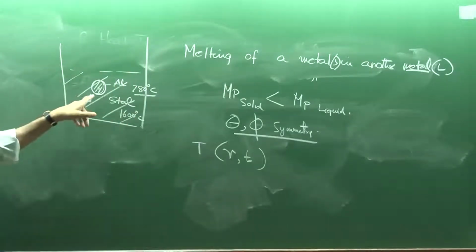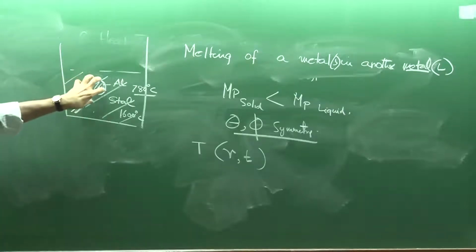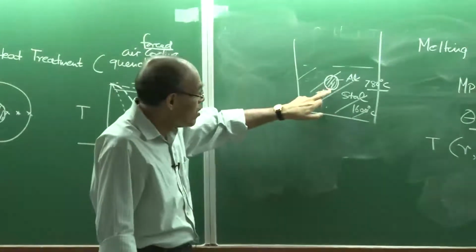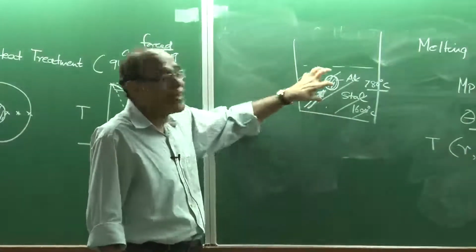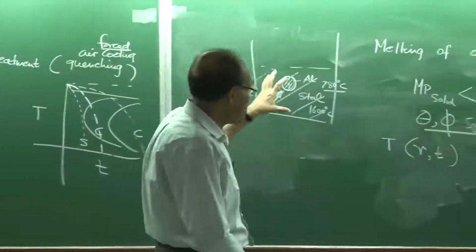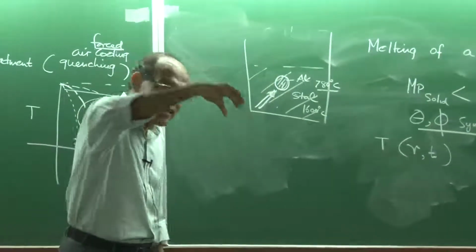So, if we look within the solid, I want to find out how the temperature distribution is. So, we are not looking outside the surface, we are looking from the surface inside, and then this becomes a pure conduction problem. Okay? And then it is an unsteady state conduction, because this is a solid sphere which is being plunged at t equal to 0.